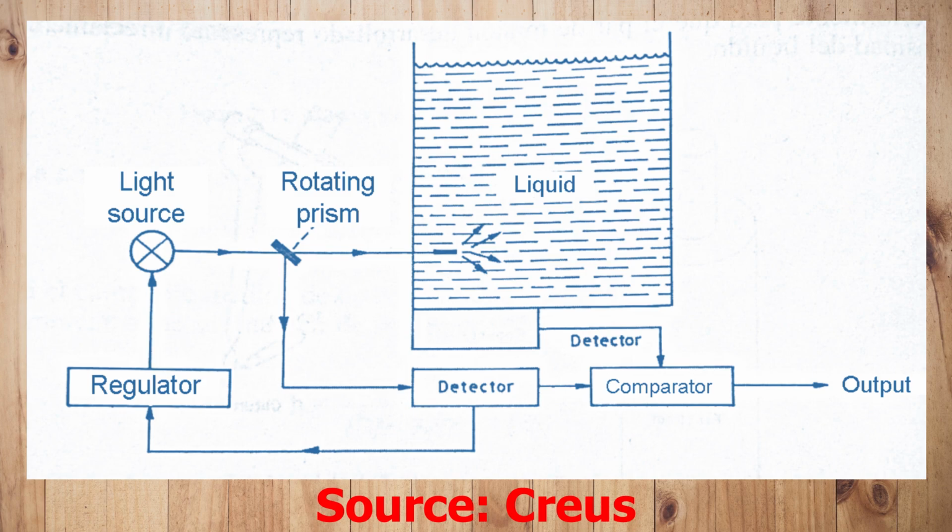Refractometers are used on clean fluids. The rotating prism model consists of a tungsten filament-like source that strikes the liquid at a certain angle, such that liquid reflection passes into refraction. The light beam is focused on a rotating prism that sweeps through the process liquid. The reflection that occurs when the light beam hits the critical angle is detected with a photoelectric cell, and the signal is amplified for its corresponding registration or control.